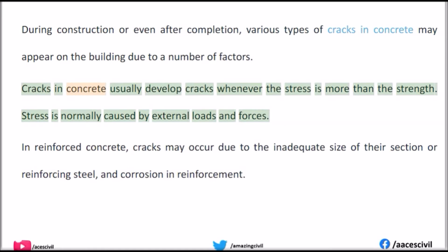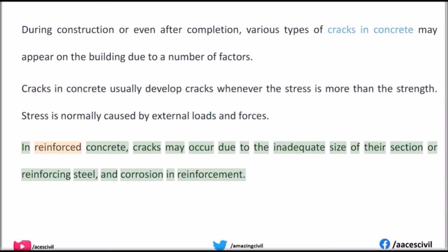Concrete usually develops cracks whenever the stress is more than the strength. Stress is normally caused by external loads and forces. In reinforced concrete, cracks may occur due to the inadequate size of the section or reinforcing steel, and corrosion in reinforcement.